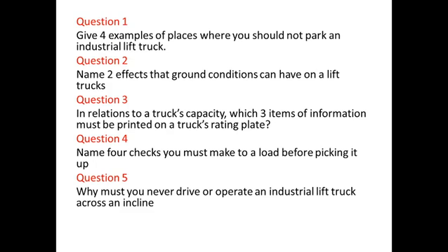Question 5, why would you never drive across an incline? Well, if you were to drive across an incline, the load would be more likely to tip off, the truck would be more likely to tip over, and ultimately the truck is not built to do that. The truck is not manufactured to drive across an incline.